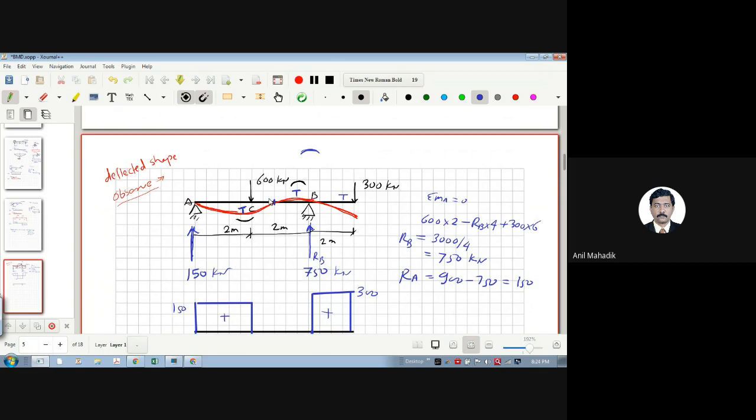Because bending moment is a mathematical equation, once you calculate that you will understand there is some point of contraflexure. Mathematically the bending moment at this point is 0. There is no deflection at one point, but rather I would say it is changing its deflected shape.